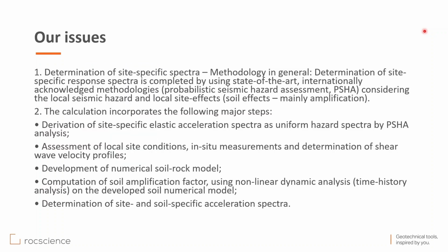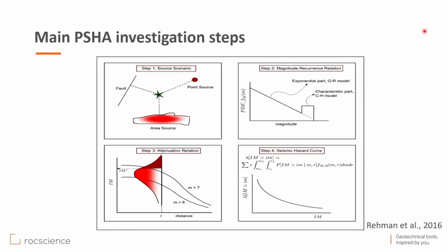Here are just some points of our issues from the previous earthquake evaluation that I mentioned. Here we carried out a probabilistic seismic hazard analysis, and let me say just some words about this. The term probabilistic seismic hazard analysis, in a broader sense, is used for all seismic hazard analysis methods which attempt to define either the frequency of events of earthquakes or the frequency of exceedance of secondary parameters, for example, specified ground motion levels.